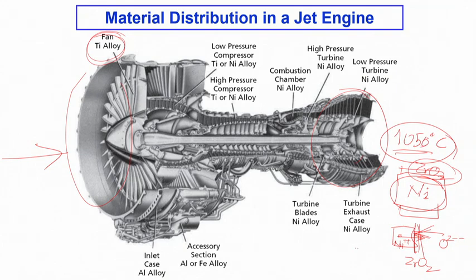But the biggest problem is how do you make sure that this zirconia, which is an oxide having a very different crystal structure, very different coefficient of thermal expansion, density, and all those physical properties than the base metal based on nickel, bonds well. So the bonding between these two becomes the biggest challenge. So all the aircraft manufacturers, for that matter all high temperature metallic systems, would always love to create a technology which can allow them to combine the oxide with the metal very nicely and very efficiently at the interface.